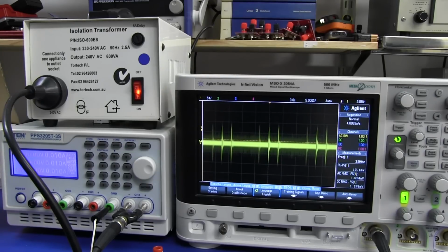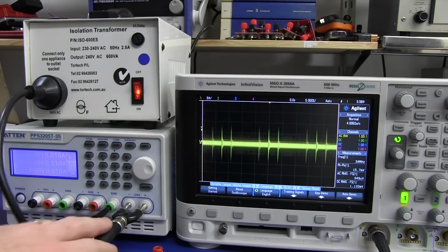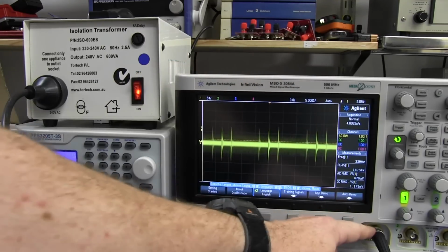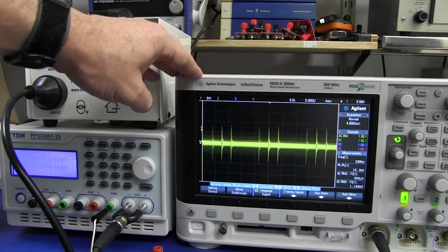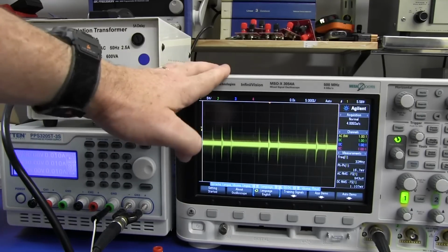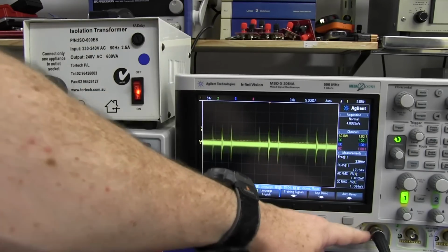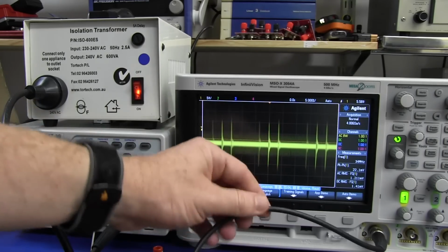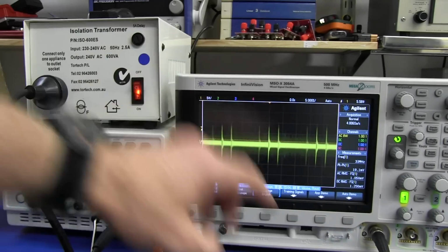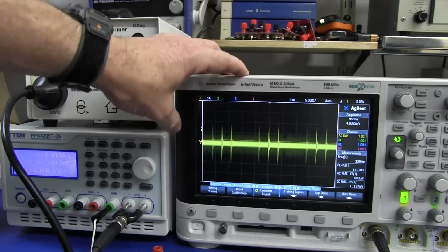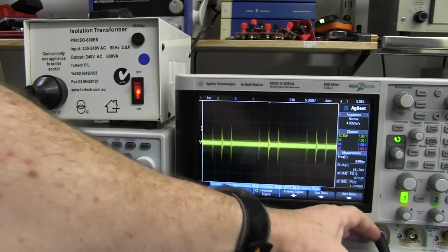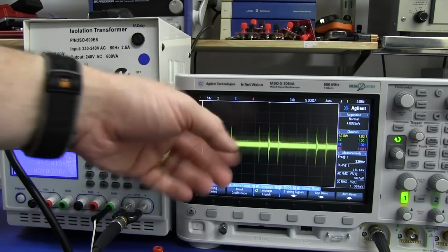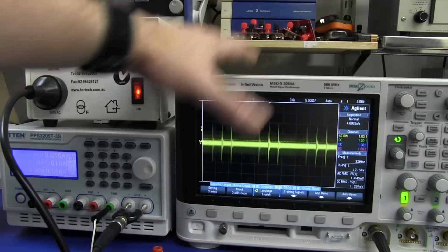Alright, so I suspect it's common mode noise being picked up through the mains system, and because this oscilloscope is mains earth referenced, and as you saw in the mysterious oscilloscope phenomenon, you can actually get ESD impulses which jump onto the coax cable, onto the lead, and then because this oscilloscope only has so much common mode rejection from the mains, it can actually generate input noise coupled through the earth system.